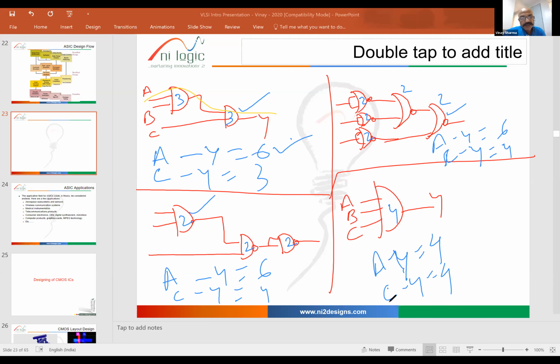So in static analysis, this is how it works. STA is a process in which you can identify at what speed the design can operate by just knowing the propagation delay of the blocks in between the data path. That's it. So this is how an STA can identify the delays in any data path.